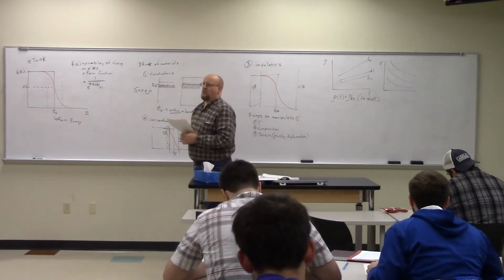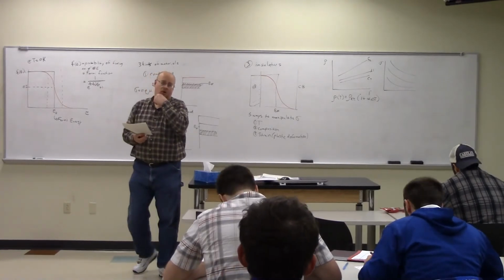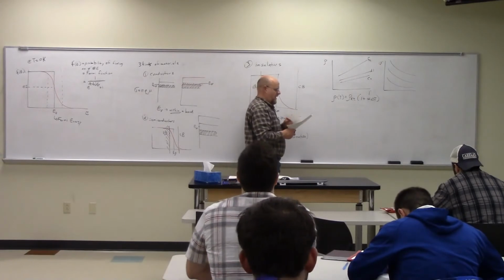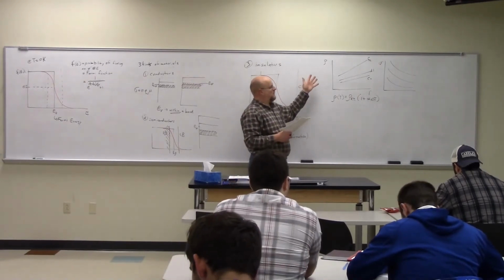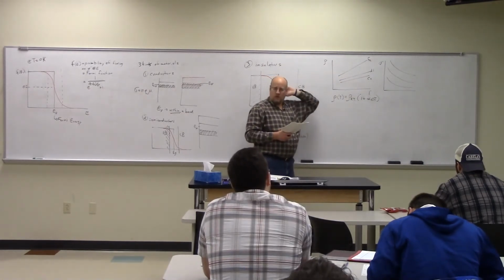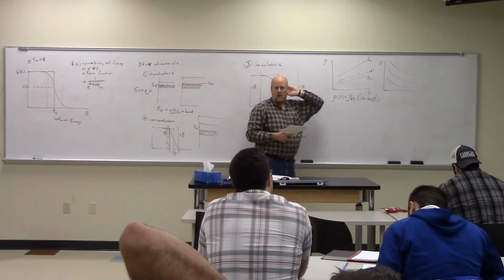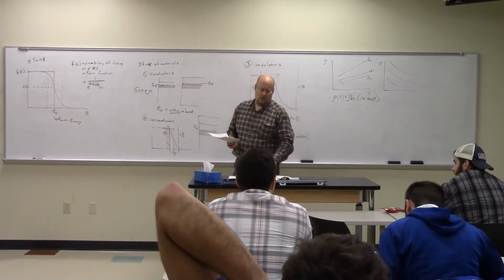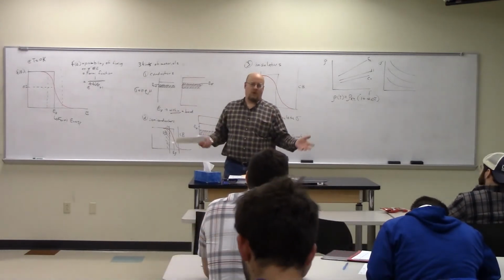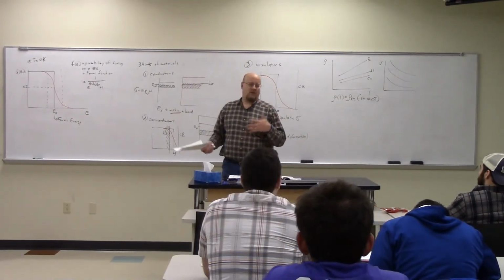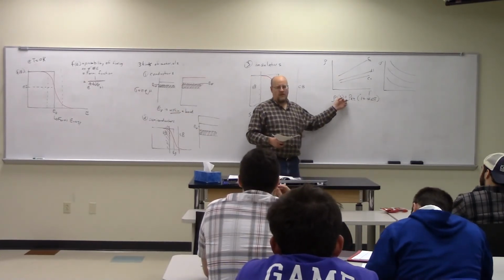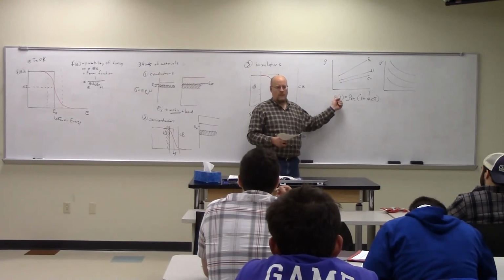So at least as long as the change in the temperature is fairly small, we can consider that there's a linear response to temperature change. If you get really large temperature changes, you're probably going to have other things going on in the thermal characteristics of the material, and you're going to be tempering your material, changing it from alpha to gamma, whatever. You're likely to be doing other things to the material besides just altering its conductivity or resistivity.